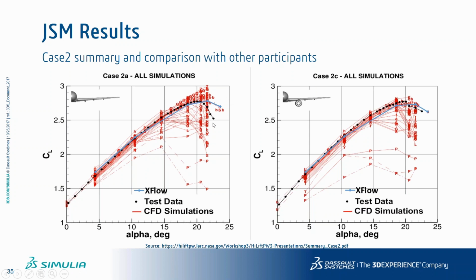But we see that almost no participant is able to go to the post-stall region, or they describe a stall entry very early. You can see here or there. Most participants overpredict the separation, maybe at 16 or 20 degrees, or some don't predict the separation at all. Only a few participants manage to get such a post-stall description of the flow. It's even clearer, I think, on the nacelle case, where the participants really overpredict the separation at 21 degrees.